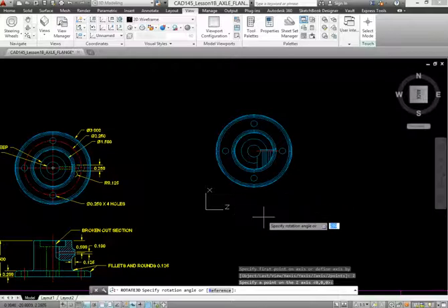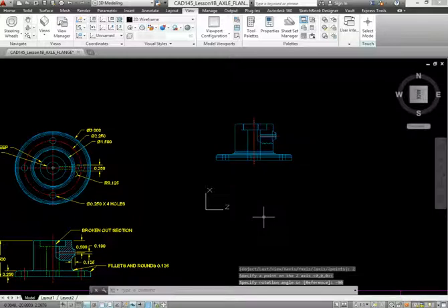The rotation angle is going to be, in this case, sometimes it's 90 and sometimes it's negative 90, depending on the direction Z is facing. It's more of taking a guess. I'm going to predict that this time is going to be negative 90, and I'll explain to you why. Yep, it was. If you put your fingers in the direction of X, and you point your thumb in the direction of Z, and twist your fingers towards you, that is a rotation of the positive angle direction. In other words, from X to towards you is considered positive. In other words, I had to rotate in the other direction, which is negative, so I type in negative 90, and it's in this orientation.